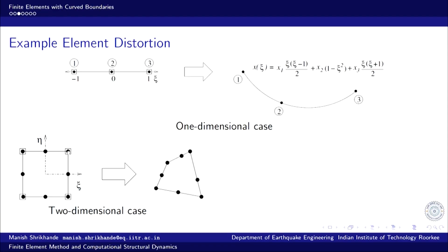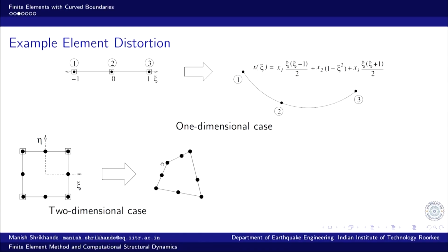So, the geometry in this particular case is mapped using the small square nodes. In this case, 4 corner nodes, so the interpolation will be bilinear. So, a 4 noded rectangle, all these straight edges will be distorted using straight lines. So, this regular rectangle can be mapped into an arbitrary trapezoid, right. Different edges can be mapped in different ways.